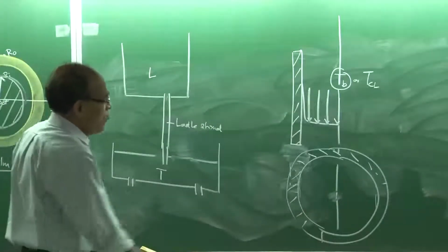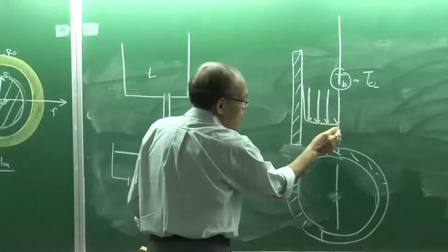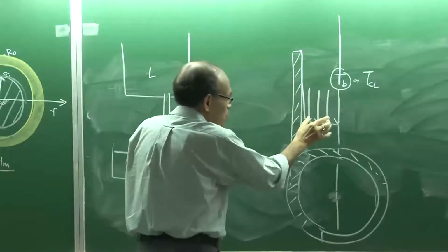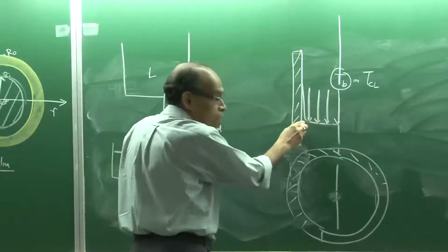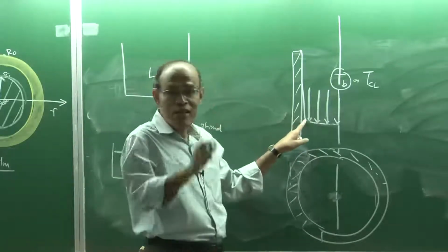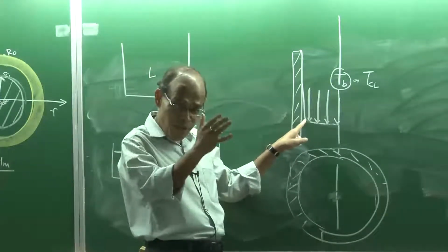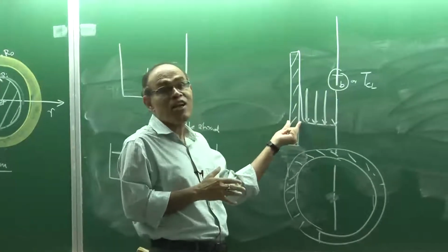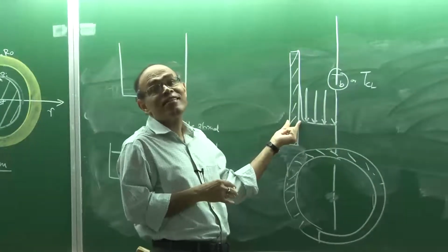From the bulk there is no thermal resistance, it is more or less homogeneous because of the extensive turbulence here. Close to the wall there is a thermal boundary layer, so there is a boundary layer resistance. After the boundary layer there is a contact resistance, and following that there is a shroud wall resistance. So that is the net rate of heat flow.